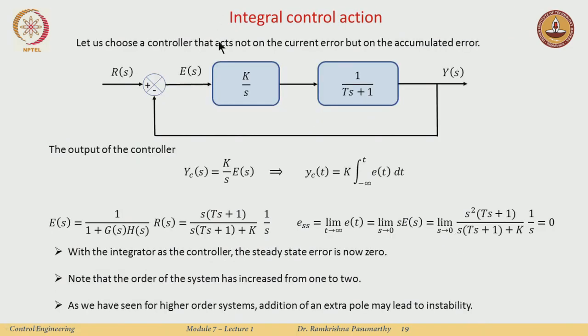Okay. Now, let us see what a pure integral control action does, and this actually goes very well with the terms, right. So, integral control action is, well, I have a k, I divide by s. 1 over s has an integral action, right. The Laplace transform of an integral of a signal just translates to 1 over s times the Laplace transform of the original signal. Okay. So, the output is again something like this.